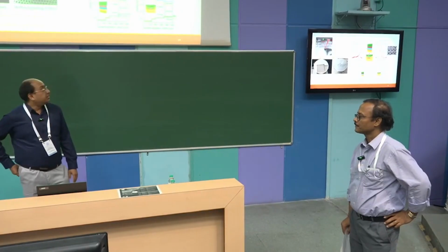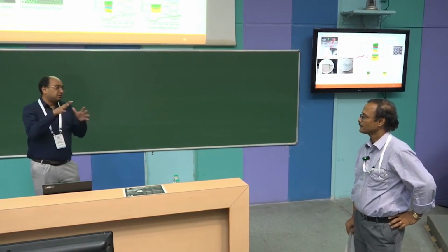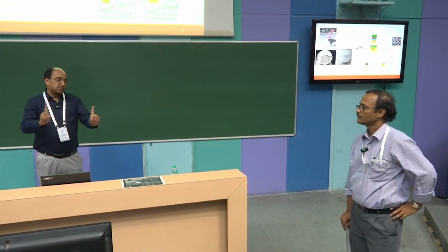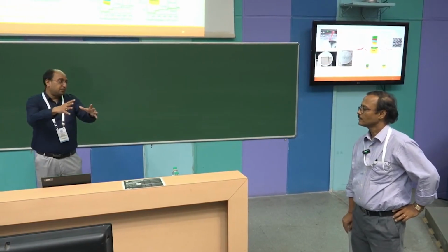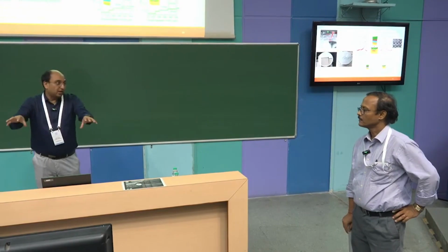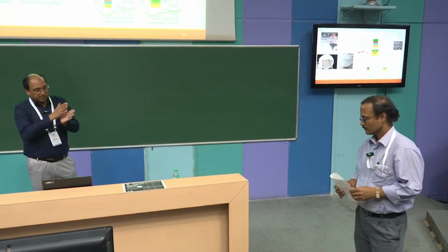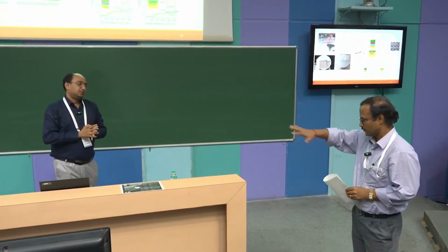I did not go into details. How we stop this Stranski-Krastanov island growth is to pump in a lot of hydrogen. When hydrogen stays on the surface, atoms don't come and form those pyramids or islands. They stick to where they land and get buried by the next growing layer. So hydrogen plays an analogous role to antimony, making this a layer.